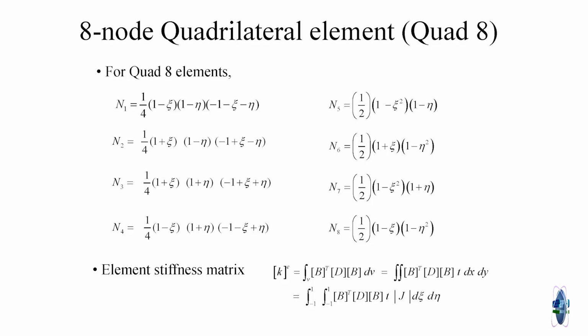If you are choosing 100,000 elements with quad 8, for each element it will be 16 by 16, that means 256 coefficients to be evaluated, that for 100,000 times. Then assemble all of them, then you will get the entire matrix Ax is equal to B. Is that making sense? So, when you press the laptop asking it to solve, this is what it does.